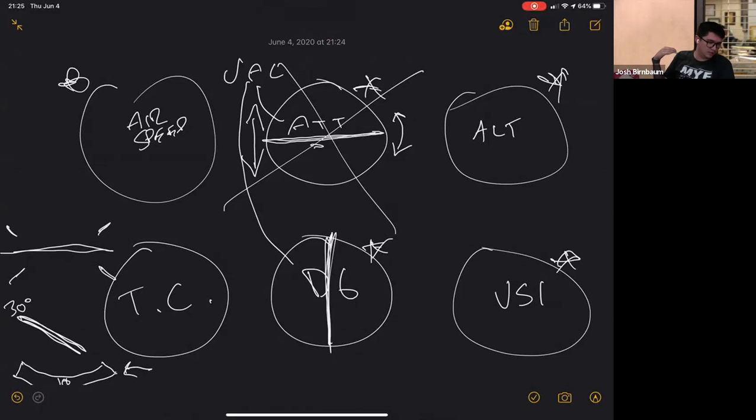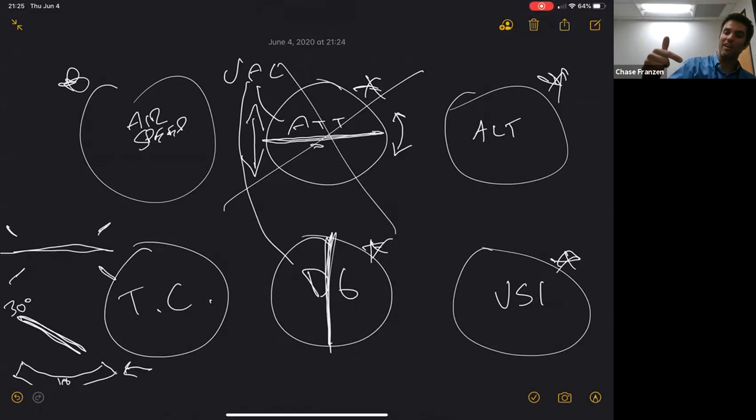So I'm looking all over this POH trying to figure out where I'm going to read up more on it, because I don't know how I got this far without ever having to explain it. It's really hard to explain. So it operates on principles of gyroscopic precession, knowing that when you exert a force against a spinning disc, that force is felt 90 degrees in the direction of the spin, but it also is rigidity in space. The canting of 30 degrees is why it can indicate both bank and rate at the same time, but I can't articulate why.